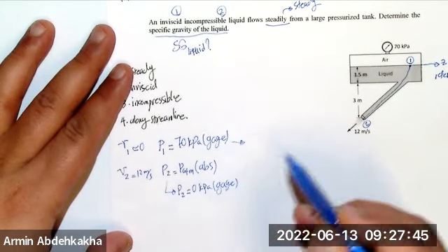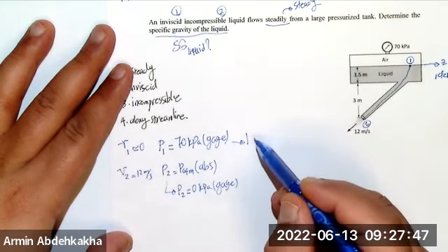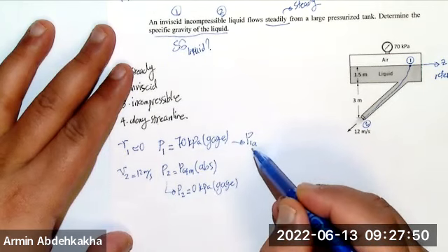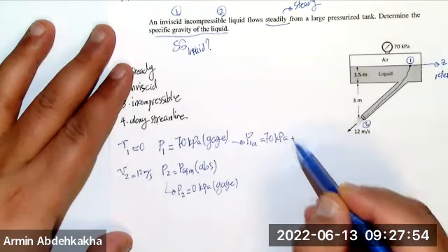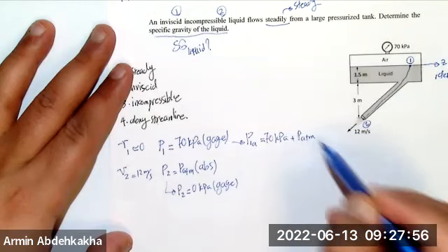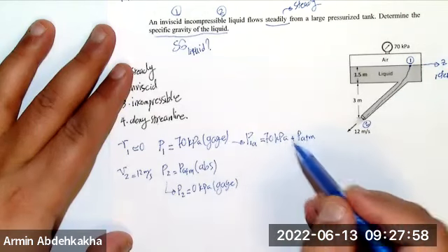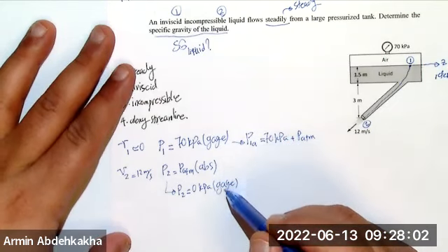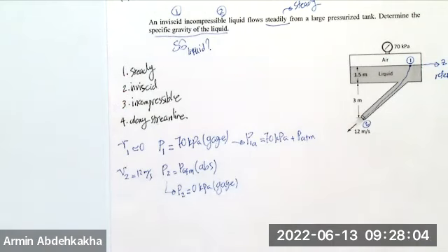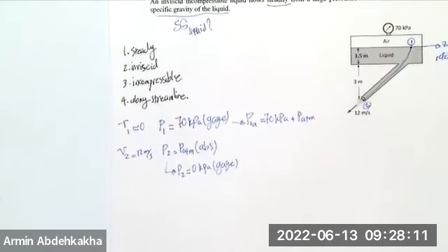But what is the absolute pressure at point one? The absolute pressure at point one is 70 kilopascal plus P atmosphere. Okay? Use P atmosphere, the absolute pressure or gauge pressure in Bernoulli, but keep that similar and the same in the whole streamline and equation that you write.